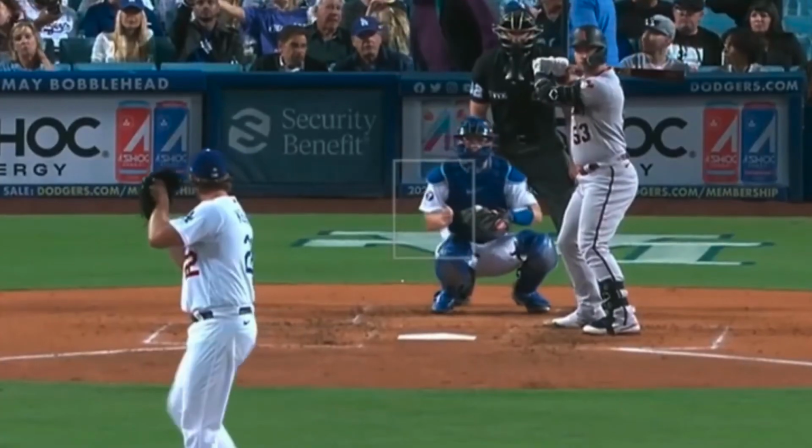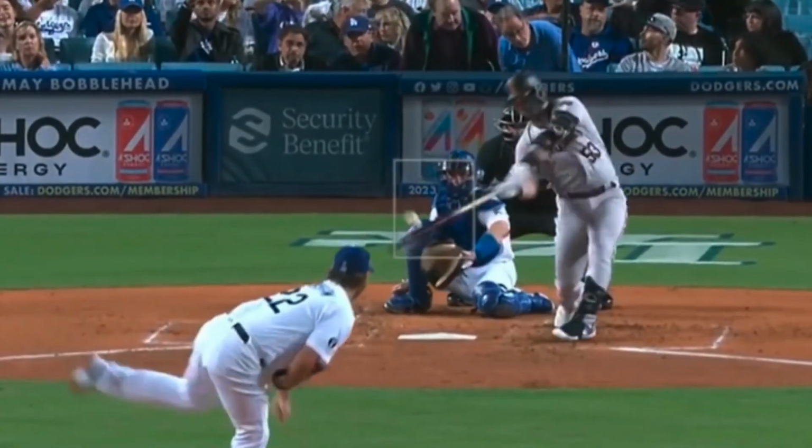Okay, so relative to the ball's spin and the flow, we're getting a lower Reynolds number here, higher Reynolds number here. So our separation will be earlier here and later here. Where it's earlier, we have a higher pressure. Where the separation's later, we end up with a lower pressure, therefore higher pressure on the top. The force will be pushed downwards. So our curveball, which travels from our pitcher's hand, is going to have a trajectory like this, and then it's going to curve downwards. Like that's our 12-to-6 curveball. Same idea we saw for the tennis ball.